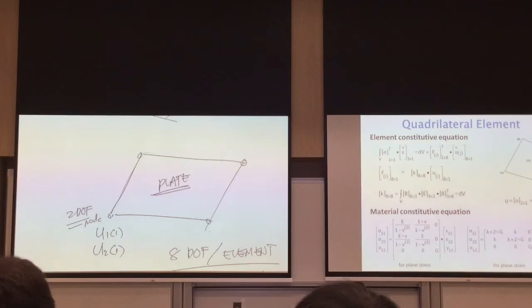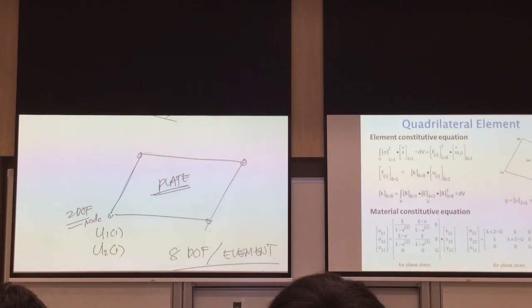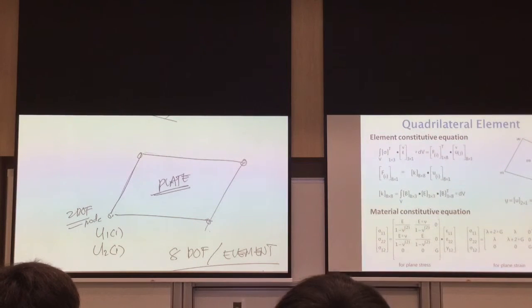So what is your stiffness matrix? It's this one here. Have a look. This one is equal to that. So it's not anymore just a single value of stiffness. It's that 3 by 3 stiffness matrix. So to simplify, it's equal to this one here. So here, for each of the nodes, it's U1, U2, which is your Ui.